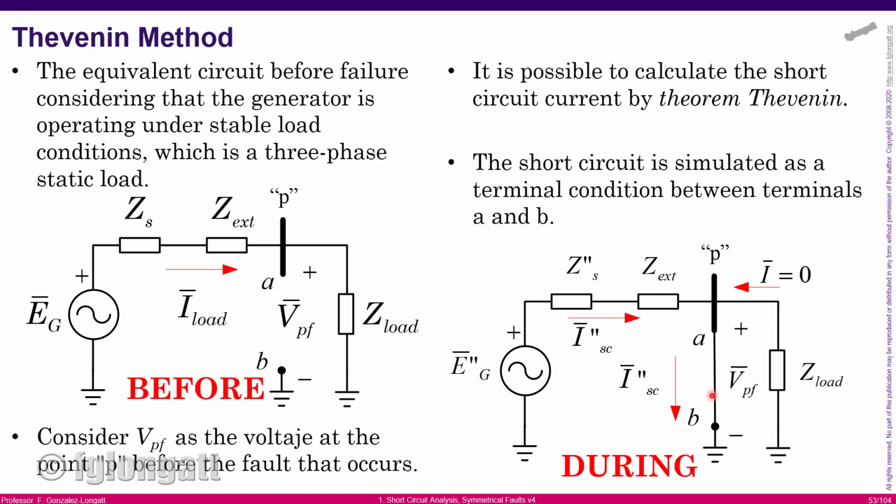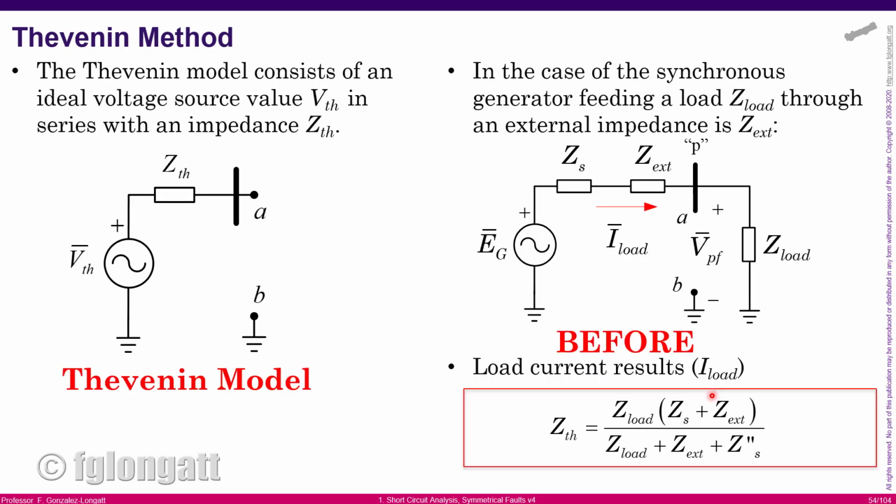However, if we want to solve this problem using the Thevenin theorem, what we need to do is create a model, and it's the famous Thevenin model. And all of you must realize that the Thevenin model is extremely simple. A voltage source in series with an impedance. Thevenin voltage and Thevenin impedance. That is the name for those components over there, okay?